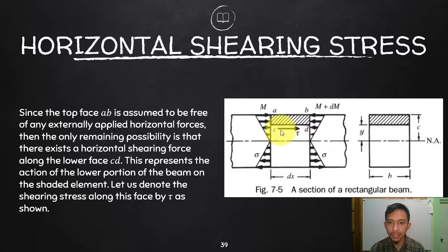Therefore, to make it equilibrium, the summation of horizontal forces should be 0. If the concentrated force here is smaller than the concentrated force there, there should be a reaction that will help make it equal. If you look at this, the area in your plane CD will help through friction. Through friction, that area will resist together with the force here in your AC to make it equal with the concentrated force in your BD.